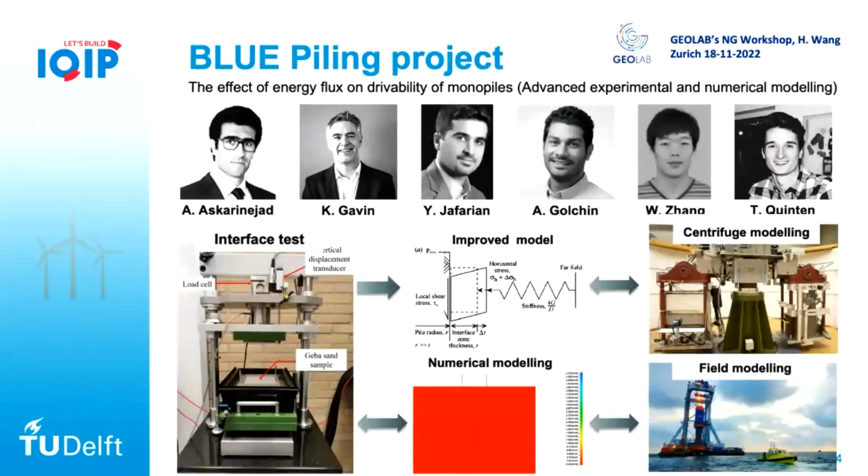And as a follow-up of that work, we are currently working on an industry joint project called Blue Piling. Basically, our industry partner developed a new concept of the hammer, and we want to test it in the centrifuge. This project will involve the interface test, numerical simulation, the centrifuge test, and also the field test. In the end, we will come up with a new installation hammer system, and also develop a new pile-soil interaction model to really simulate the whole installation process.